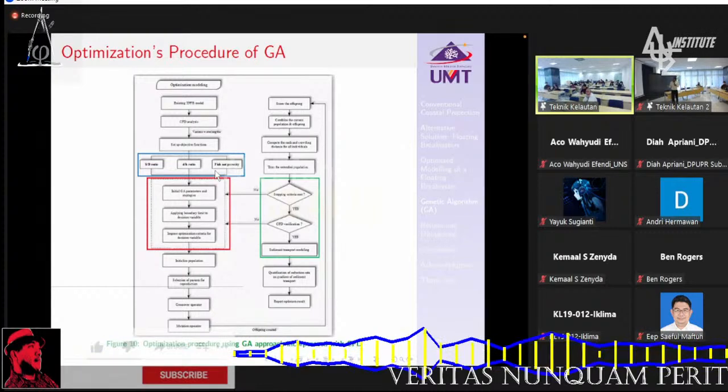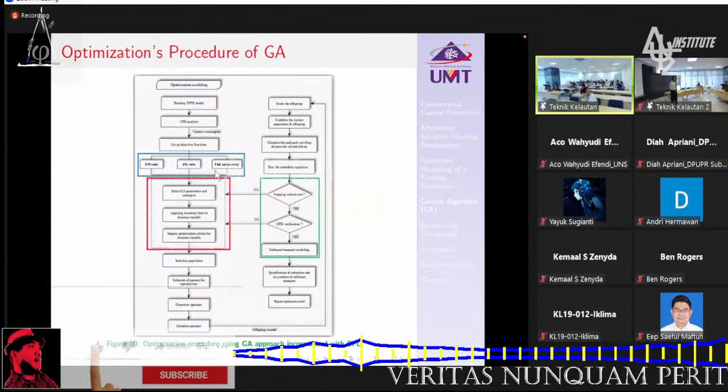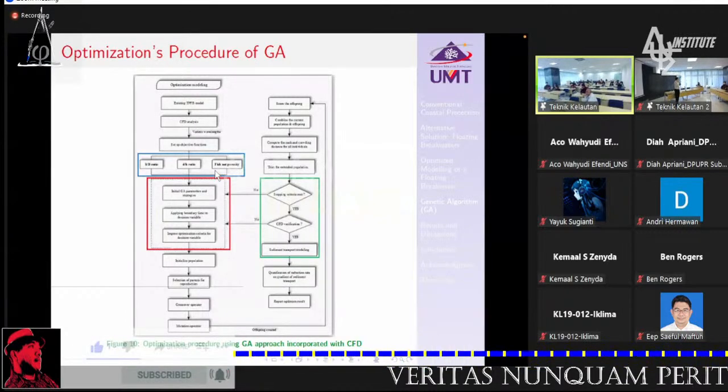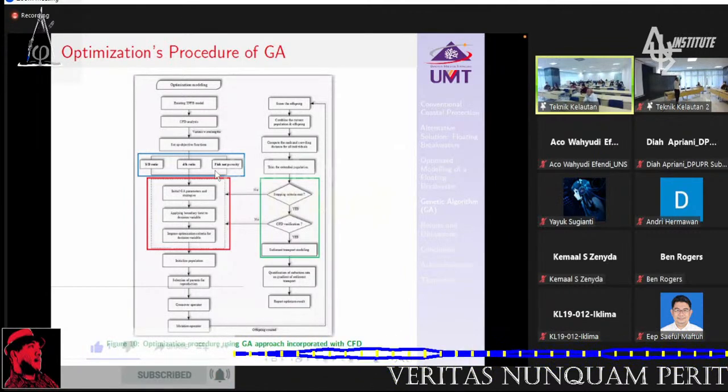One more interesting point in our optimization is that it is not purely theoretical, because sometimes the candidate for the optimum design obtained from MATLAB is not fully proven when we evaluate it with CFD. Once we have the ranking of the best candidates from the 4,000, we list maybe about 10 candidates and examine them one by one.